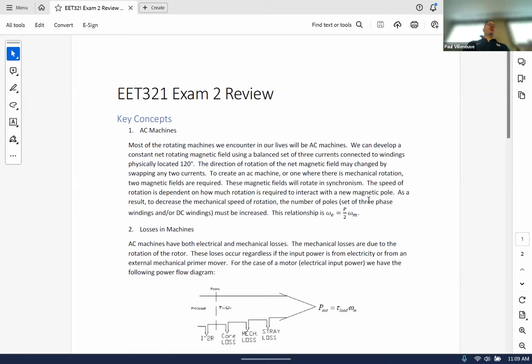It's not going to be consistent torque. Either the motor is going to get damaged or the pump is going to get damaged. It's not something you want to do. All right, so that's why when you buy motors, anything most likely above 10, maybe 15 horsepower is almost guaranteed to be a 3-phase motor, just because other motors just don't last that long.